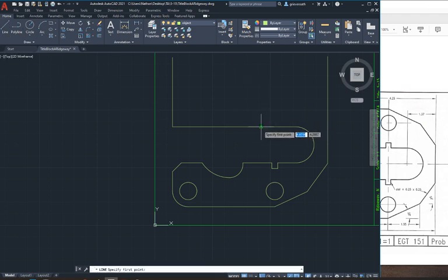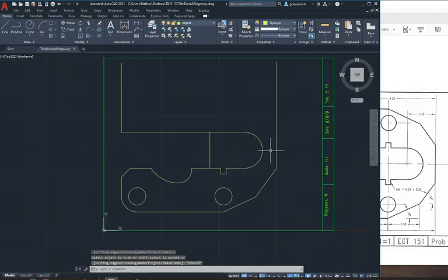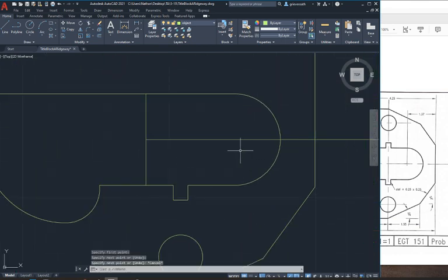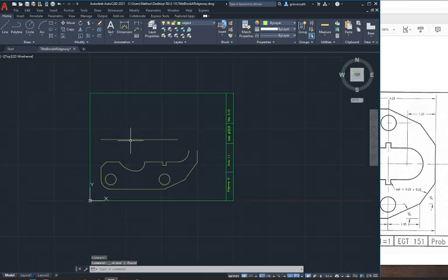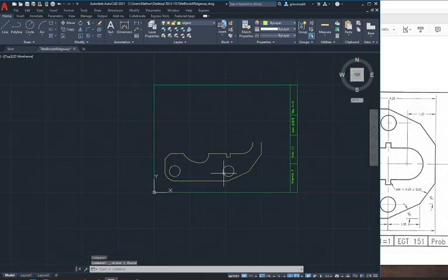So I'm going to take my line tool here, anywhere. I'm going to draw it through, escape, use the trim tool, escape. What I'm trying to do here, I'm just trying to get a center line. So I'm going to select here and draw this through. Escape. The next thing I'm going to do is I'm going to use the trim tool, and I want to trim these two lines. Escape. I'm going to delete what I just drew, as well as anything above this, where I only have my half drawing right here.